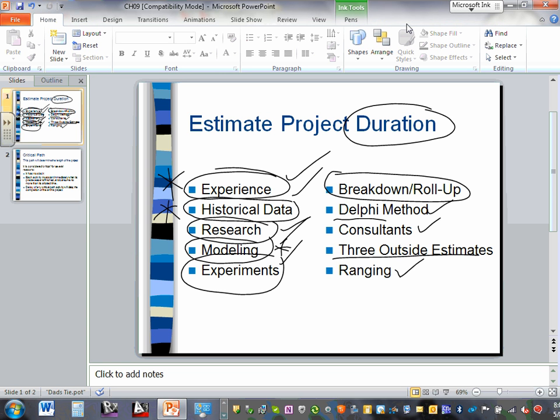Any comments, any questions? But this is how you analyze the network, analyze your critical path, CPM, critical path method, which you're looking at. We're going to look at it in a second. So we take every activity item, we assign a minimum possible start time for it, and the duration, and the earliest possible finish time for each one of them. You break it down and add them up. So we got that one.